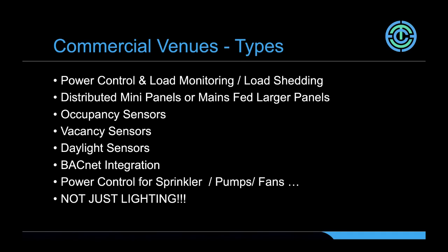So some of the highlighted points when we look at commercial venues that ETC shines on, and we can really take advantage of some of their technologies, are in the power control and load monitoring realms. And when we talk about load monitoring, we're talking about the ability to give real-time data for the actual power or wattage of electricity being drawn on each of the circuits in real time.